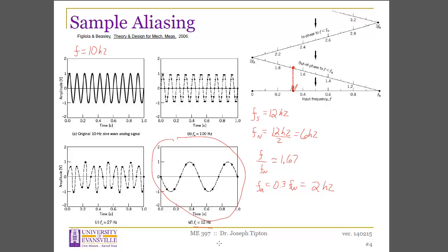Note that we have the 12 Hertz sampling rate, and you can sort of match this to the picture above. If this is the original signal, I'm taking a sample every 1/12 of a second. So I take my first sample here. My next sample is taken somewhere here. I'm matching these dots up on this screen.